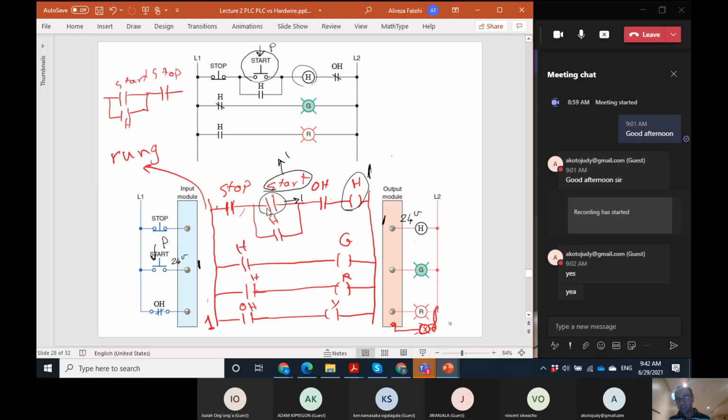Something that we need is the logic is 1. So they are the same. It means that we need a buffer. So the type of this contact must be normally open. Let me remind again. Normally open works as a buffer. A normally closed works as an inverter. Here they are going to be the same. So a buffer. That's good. That was not that difficult, but let's look at the stop push button this time.